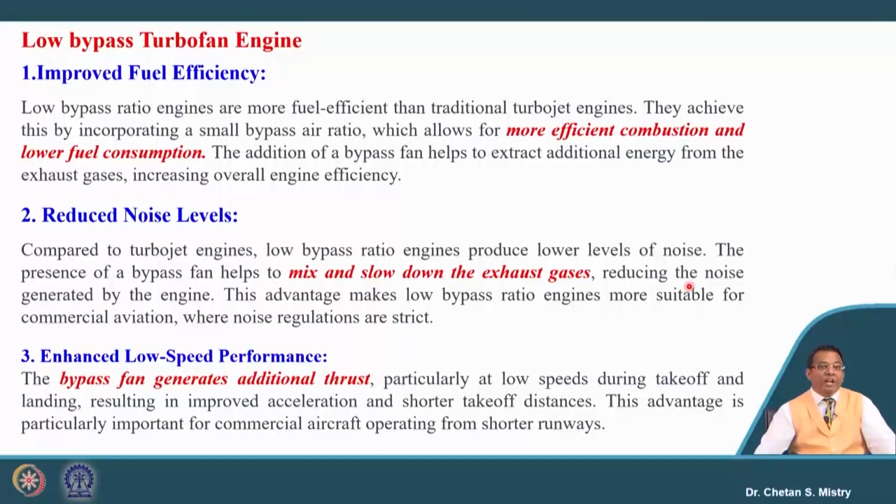Similarly, we have an enhancement in low speed operation, because the bypass fan generates additional thrust, which gives us better low speed operation, such as takeoff and landing. It also improves the acceleration and shortens the takeoff distance. That is the reason why this permits the aircraft engine to operate at shorter runways.